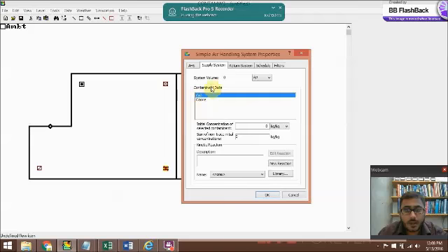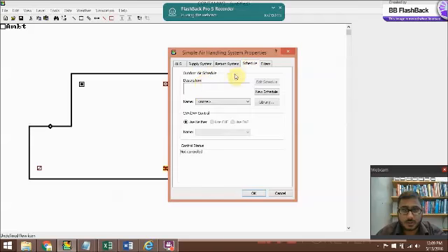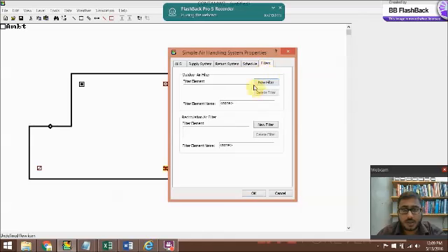If you know that contaminants are going to come from outside, you will have to specify that in the supply and the return, not over here in the air handling systems. Your schedule would determine how much outside air or timings are coming, and similarly, if you have a filter which is stopping any contaminants like ozone, you'd have to add a new filter for that.